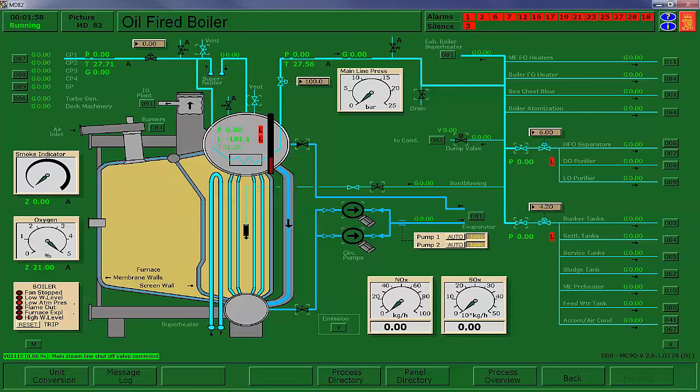I want to produce, once this is producing steam, I want it going out to the system. That will put a little bit of load on the boiler. Again, I want to bring this boiler pressure up slow. I don't want to bring it up fast. And it'll also warm up all the steam systems and start bringing back the liquids, and it'll prevent water hammer.